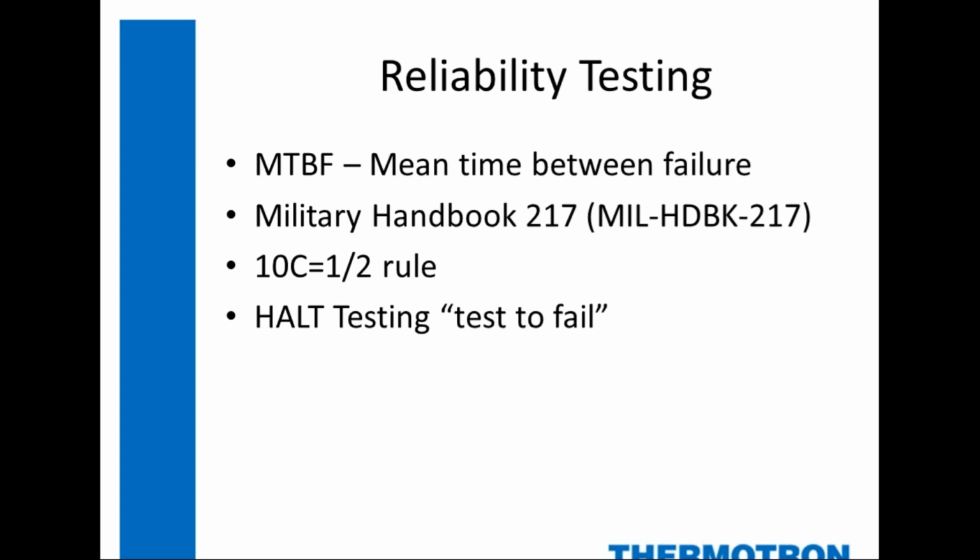So the equipment itself, it's vibration, it's extreme temperature changes, and the vibration resembles a bunch of jackhammers on the bottom of a test plate, and it subjects that product to really high vibration levels, something it would not see in the field, but trying to stress the product to an overstress situation, trying to find the weakest points of the product. I'm not going to dive into that real deep. If HALT testing is something maybe you've heard about or want to find out more, just do an internet search for Thermotron HALT Testing Handbook, and you can download a pretty comprehensive guide on what that's all about.